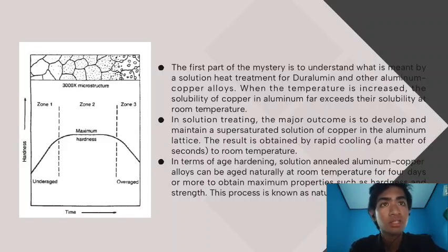In zone 1, submicroscopic precipitate particles are being formed as the alloy attempts to reach equilibrium. Solute atoms diffuse through the solvent lattice and segregate to form a few very small particles, states in which solute atoms are grouped or rearranged so they can begin to form precipitate. This results in a slight increase in hardness.